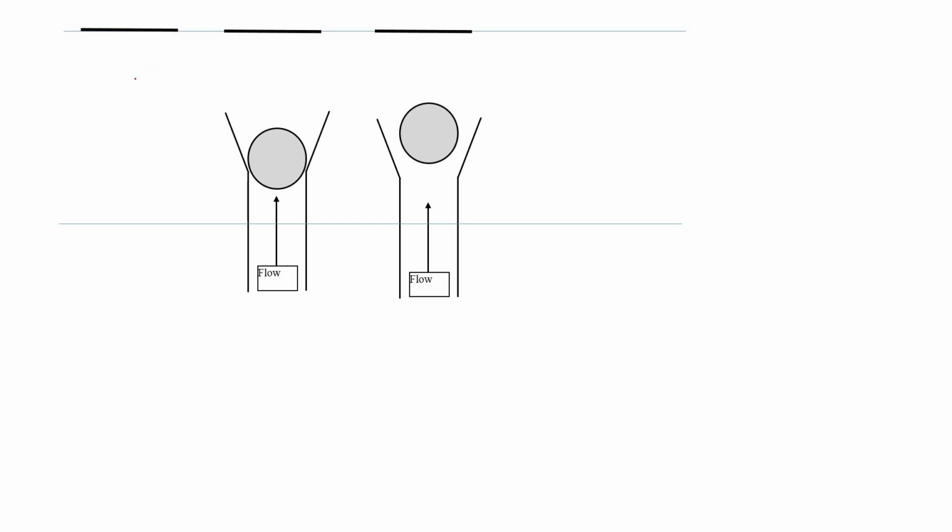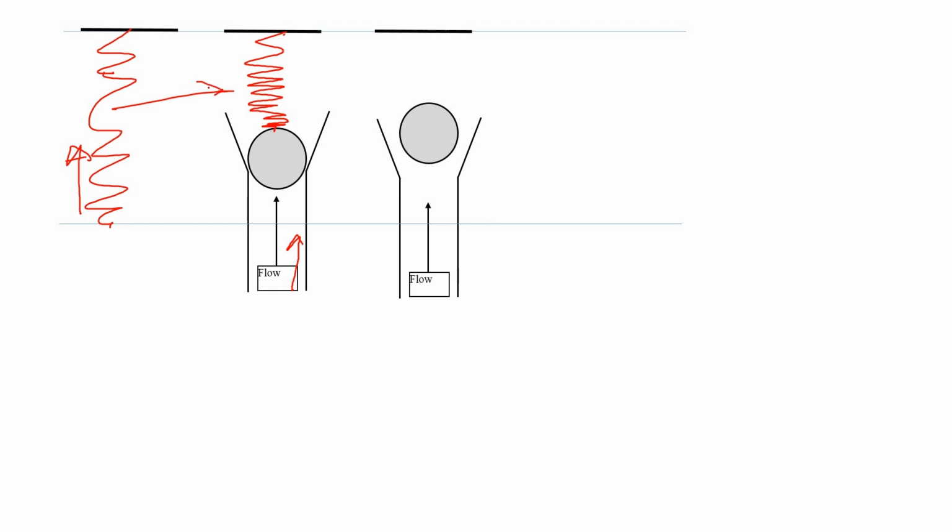On pressure relief valves. Pressure relief valves are typically designed by using a spring. So imagine that you have a spring like this. So this is the original length of the spring. Very nice drawing. Now, assume that there is a flow coming from this pipe, and this ball is kind of stressed or compressed by this spring. So we compress this spring and put it here like this. So it applies a force this way.